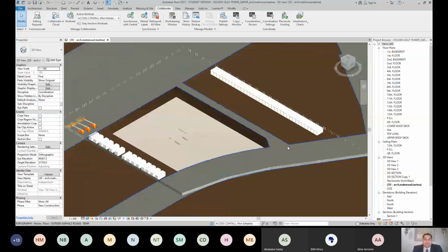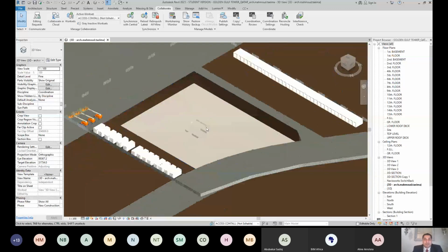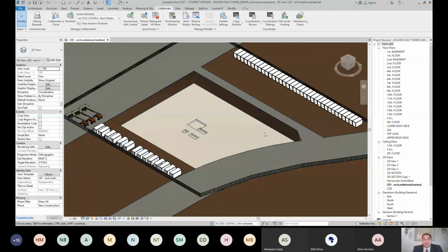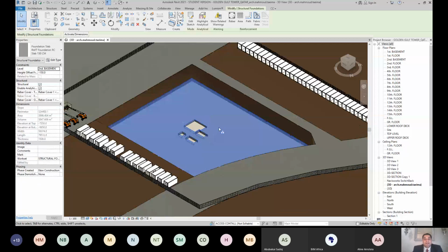This is the first shape of the site, including excavation work and mobilization for starting work. And this layer for the foundation is the raft foundation, consisting of three layers: plain concrete, reinforced concrete, and the insulation between.